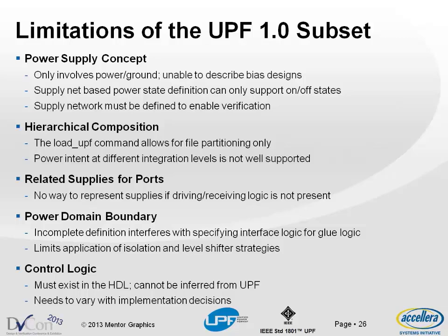There are some differences in the way we model domain boundaries. I'll get into that as we get there. And last but not least is we now have the ability to define control logic in UPF. This is a significant improvement because now you don't have to have thought ahead and put all the control signals in the design.